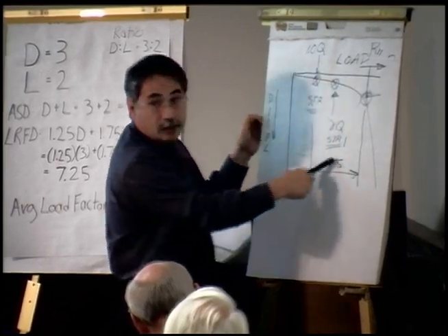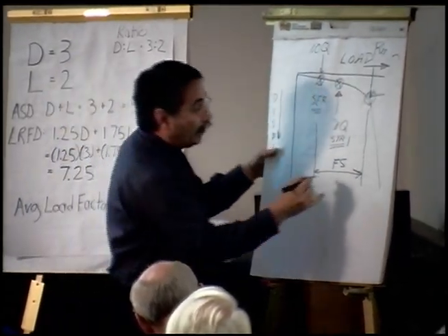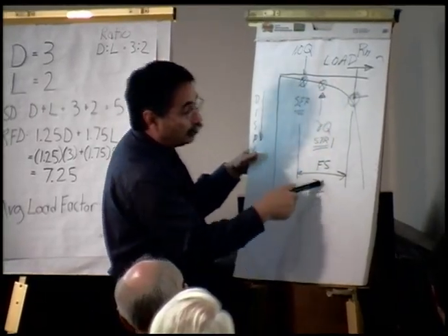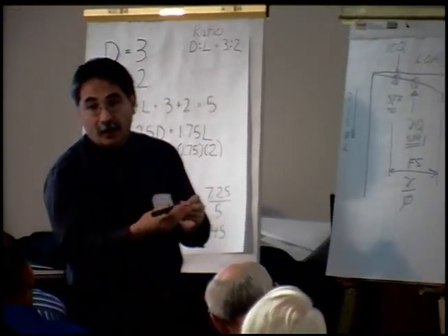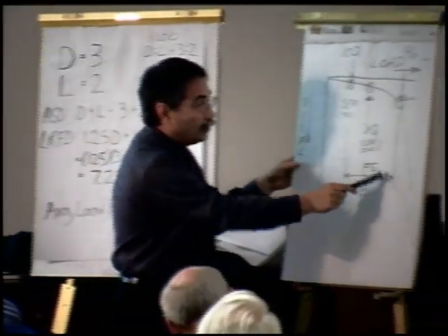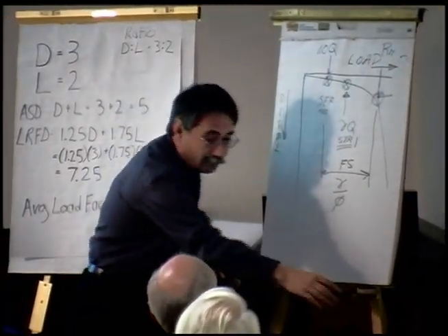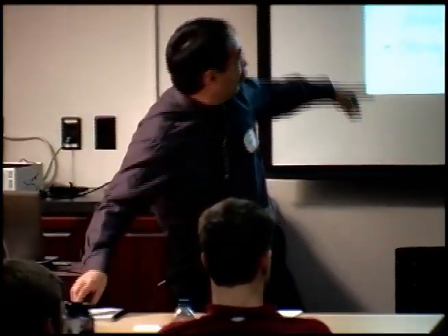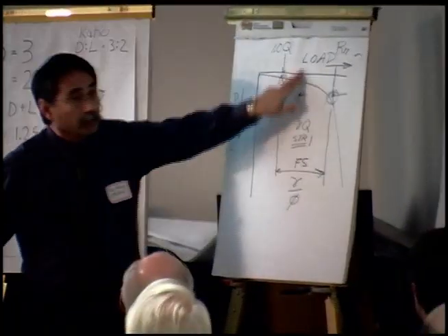This is what we've always done. And all that is gamma over the resistance factor. So it's the load factor divided by the resistance factor. And that's LRFD 101. Does that make sense to everybody? So when we talk about strength 1, we're here on this curve.